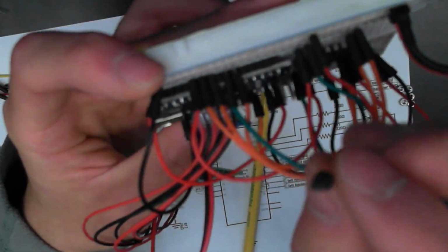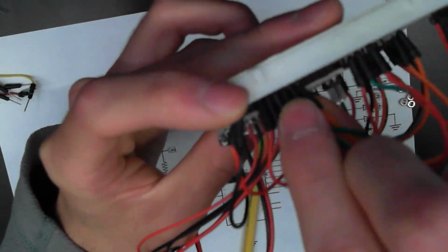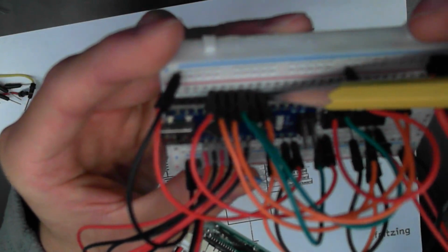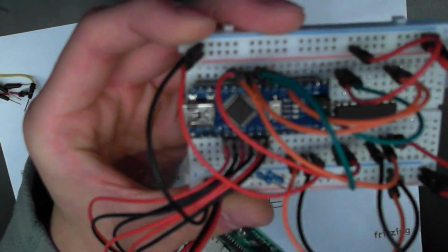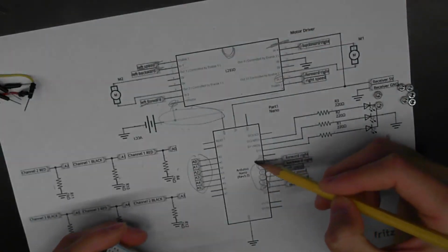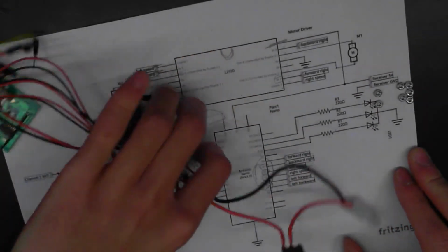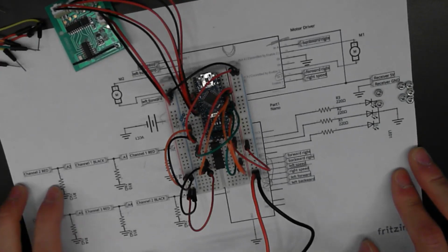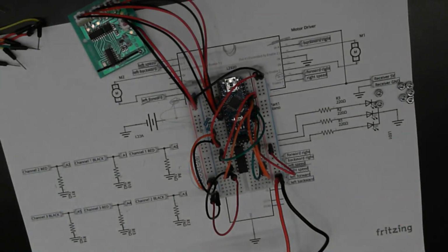So we're going to take this wire and shove it in the middle there, like so. And if you did it right, there should be no gaps in any of these pins, and they should be starting at D3 and going all the way to D8, as you see here on the schematic. So that's everything you need to do for the motor driver. Now we need to work on the pull-down pins that I mentioned earlier.